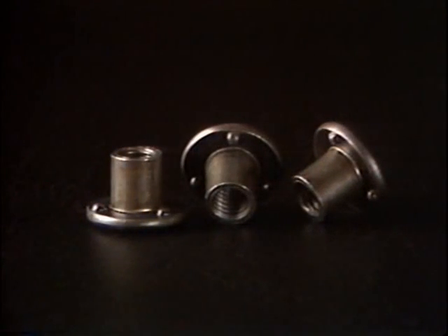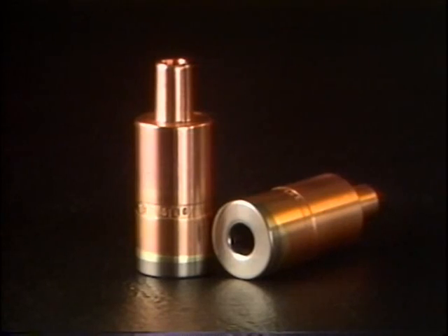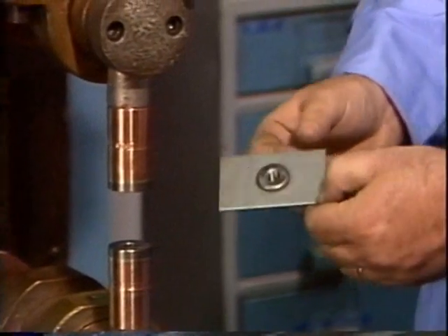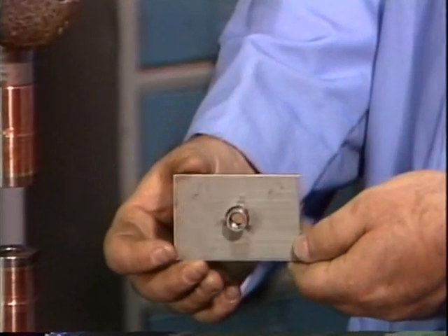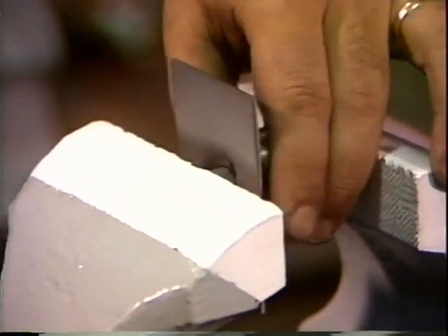The heavy-duty RH flange weld nut has 3 projections under the head and is designed for through-the-sheet locating. Because of the projection's generous size, the part can weld to a variety of material thicknesses. The long body provides extra thread engagement and a bearing surface or a structural support. When welding this type of part, an insulated lower electrode is recommended. Even to the 14-gauge material, there is little discoloration or heat marking on the underside of the weld. By using a direct push test, slugs are pushed from the sheet.